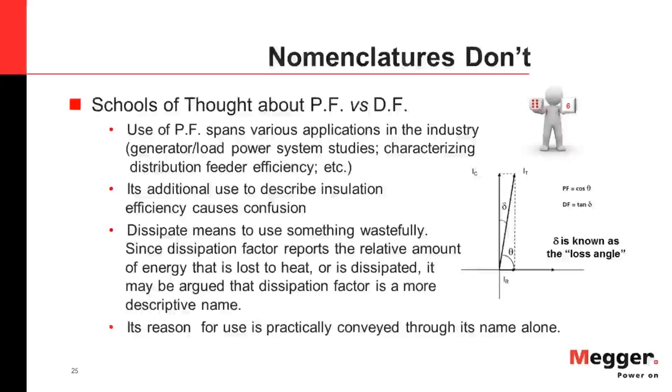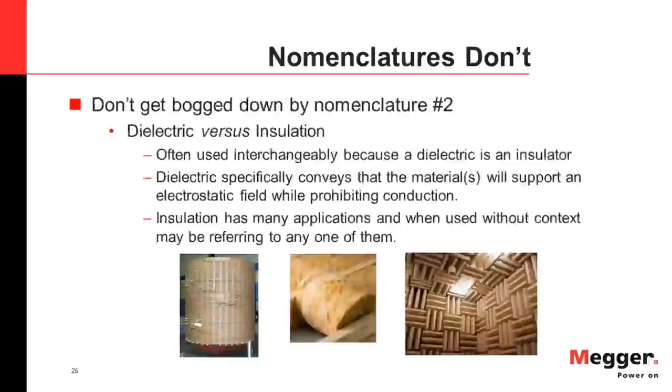Secondly, don't get bogged down by the use of dielectric versus insulation. They are often used interchangeably because the dielectric is an insulator. The use of the term dielectric, though, conveys specifically that the material will support an electrostatic field while prohibiting conduction. Insulation, meanwhile, has many applications, so when you use it without context, you may be referring to any one of these applications. And I'm showing here examples of electrical on the far left, thermal in the middle, and acoustic or sound-absorbing materials on the right, all used and talked about as insulations.